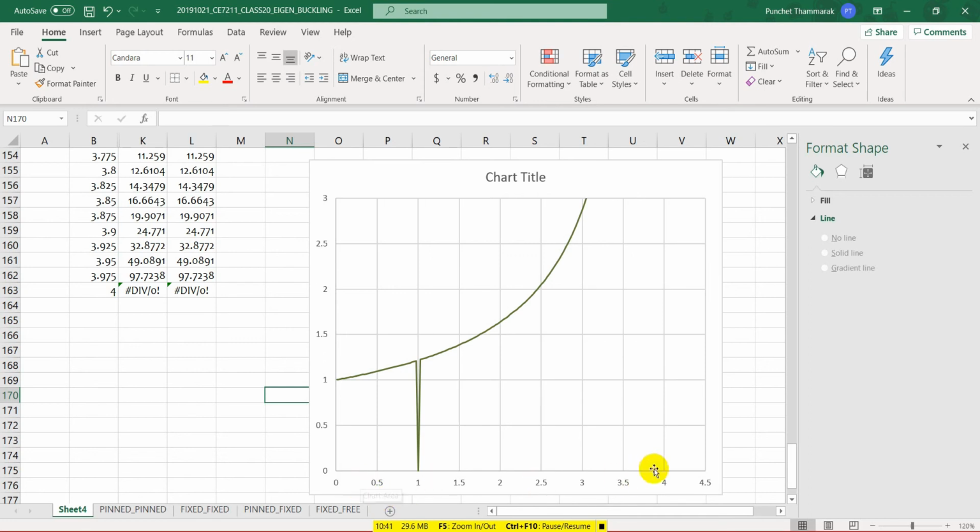I just gave you the side for the compression, so you figure out another side which is for tension. All right, that's the first thing. The second thing, as you have the M and you have the RA, both M and R, that means you now can complete the deformed shape equation y of x.